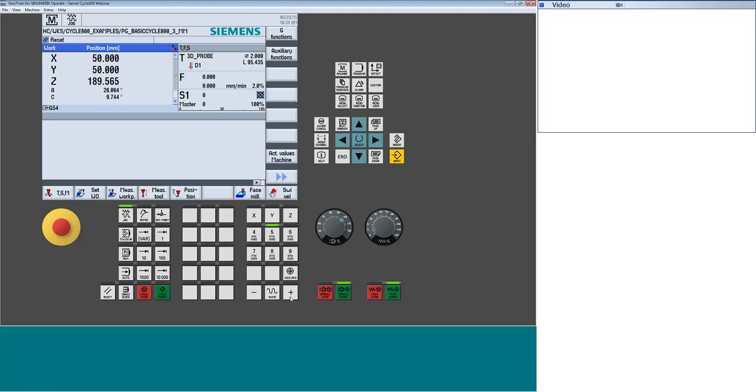So quite commonly, as I start to position around, I can use this or the hand wheel. Certainly the hand wheel, I would select whichever axis I wanted to spin, potentially pick an increment, one of these 1, 10, 100 for the index or the distance from each click. And then I can start to move the machine around with that hand wheel. Now, once I've moved it around, I may want to get back to a set position or a 0 location quickly.